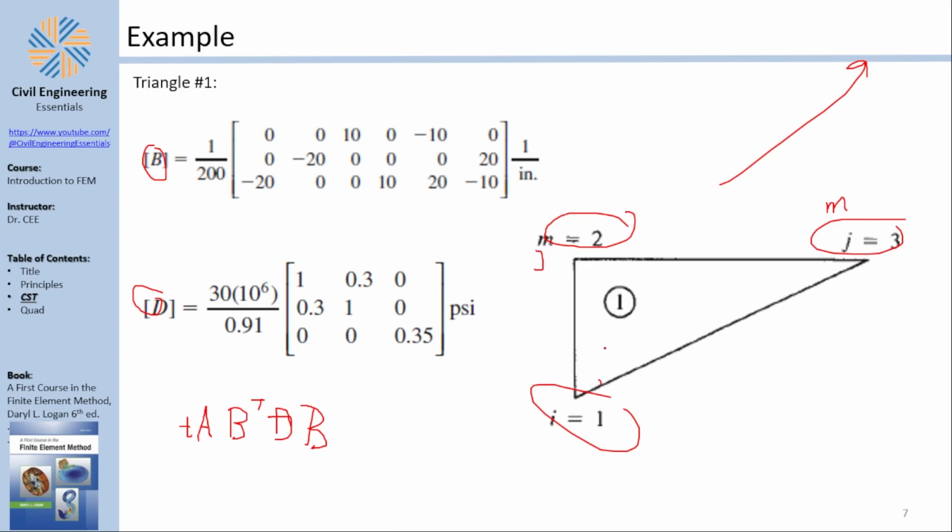But the idea, at least that you understand this, the idea is that he wants to define a counterclockwise rotation for ijk or ijm. The reason behind this is because this plane element doesn't have only 2 axes. It actually has 3. It has a local x-axis, it has a local y-axis, and it has a local z-axis perpendicular. This is x, this is y. It has a local z-axis perpendicular to the paper. And when he assumes a counterclockwise rotation, the z-axis is going to be towards you, dear viewer, by using the right-hand rule with x and y. The z is going up.